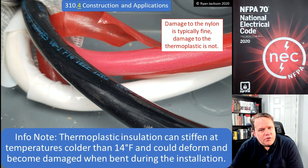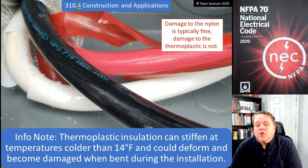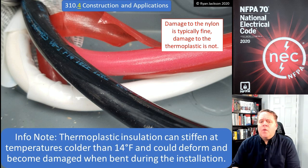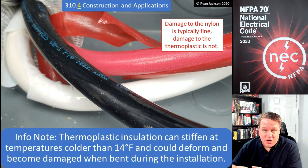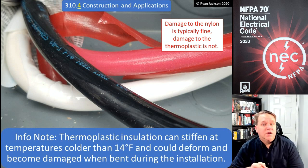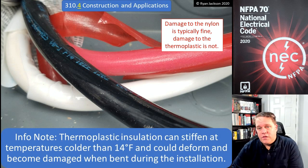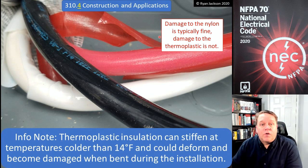And then there's an informational note, and it's worth reading, especially if you're in a cold environment like I am. It says thermoplastic insulation can stiffen at temperatures colder than 14 degrees F and could deform and become damaged when bent during the installation. So we want to be careful that we're not installing it in too cold of a temperature. Thermoplastic like THHN or THWN, those of us that have installed it in cold temperatures can attest, it gets miserable to work with. And a lot of times what will happen is the nylon will crack and come off of it.